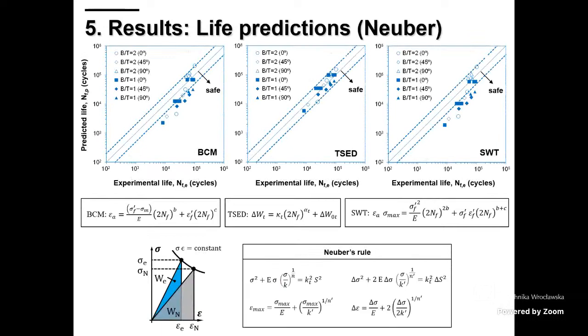So here are our predictions in terms of multi-axial loading. In this first slide, we compare the 3 methodologies using Neuber's correction. As you can see here, the models behave differently. In this case, the results are very good, in our opinion. In the other cases, we cannot say the same. So energy is very good, but the other 2 approaches led to conservative values.